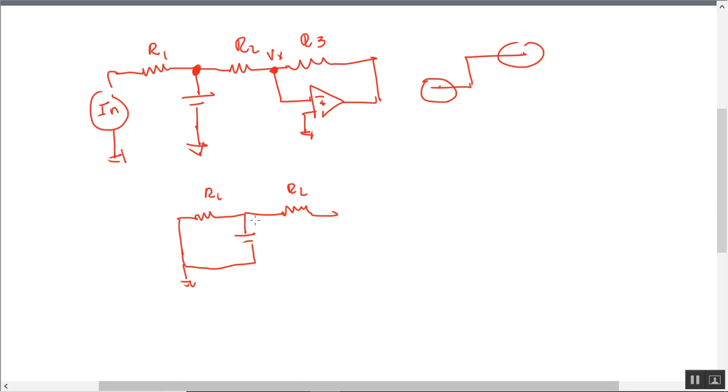Tau would be RC because, you might think, well, the op amp is acting as a buffer. And it does. However, this is at ground, a virtual ground. Current does flow into that resistor. Now, yes, this is true. In this example, the current in here is 0, so the tau is RC here.